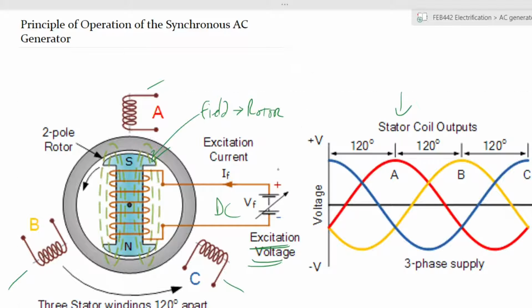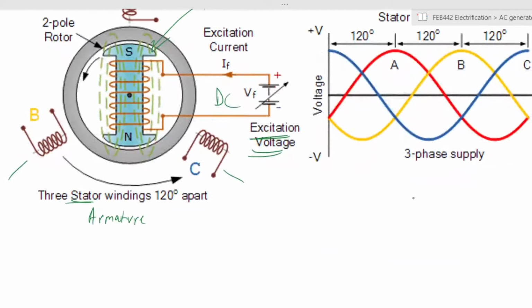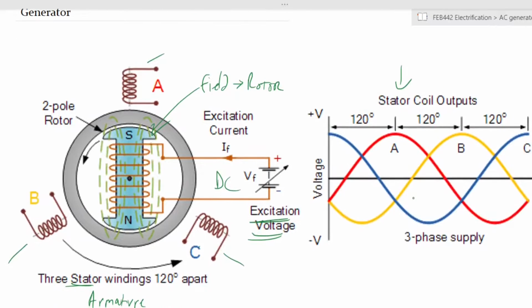So once you have that magnetism, you have your rotating magnetic field inside the rotor. Then, of course, by induction, you have windings on the stator, which will have voltages induced in them that look like that. So you have your three sets of windings, here we are calling them A, B, and C, into which your rotating magnetic field will induce a voltage. That voltage has a three-phase characteristic or an AC characteristic, and it will have a frequency.